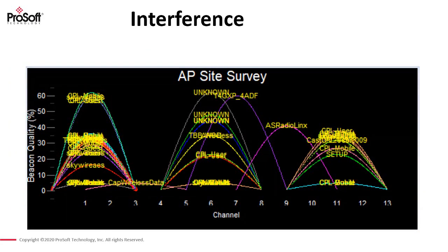The other thing, before we do any kind of radio installation, is to check what radio signals are there in the first place. So we want to make sure our radio signal is clear, and we also want to make sure we don't interfere with existing radio equipment. In this particular instance, they called us up, we went through and did a quick scan, and it turned out the IT department was installing radios interfering with the production. So we changed the antenna type, we changed the frequency and the band, and then everyone was happy.